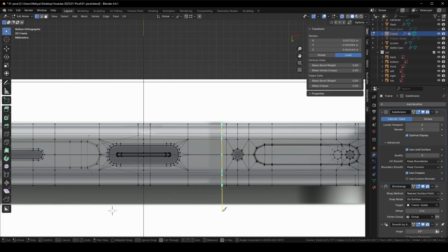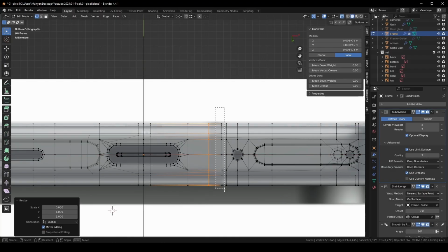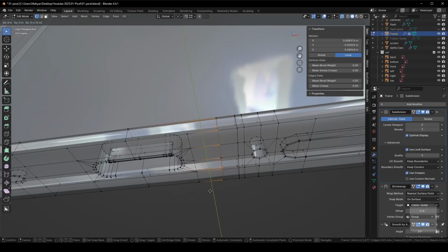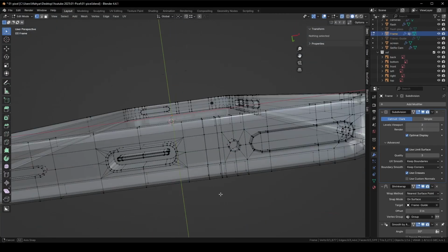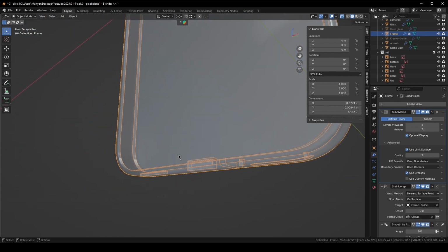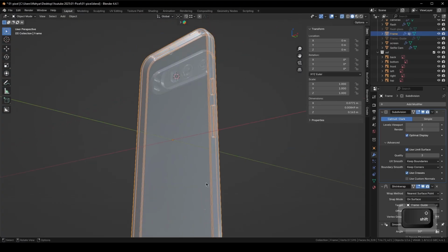I click Enter, K, C, Enter. Now, to have a perfect vertical line, we have to scale these vertices towards the x-axis, S X 0. Now we can safely press V and separate this antenna part. It's now completely ready for the shading process.